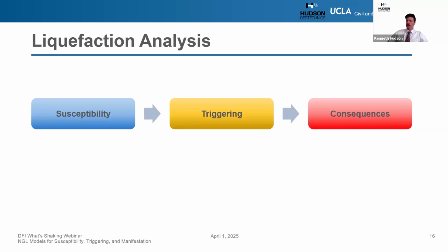And those two end members are basically just a frictional, non-cohesive material is sand-like and can liquefy. And clay-like materials will develop their strength through their cohesion and not through frictional physical mechanics and more chemical mechanics.